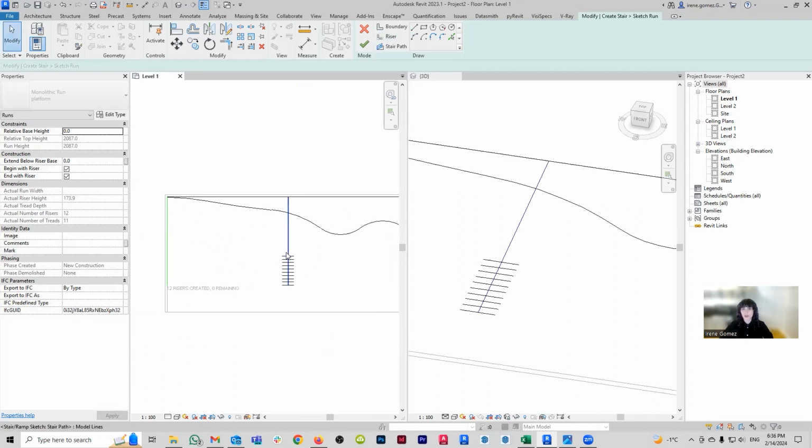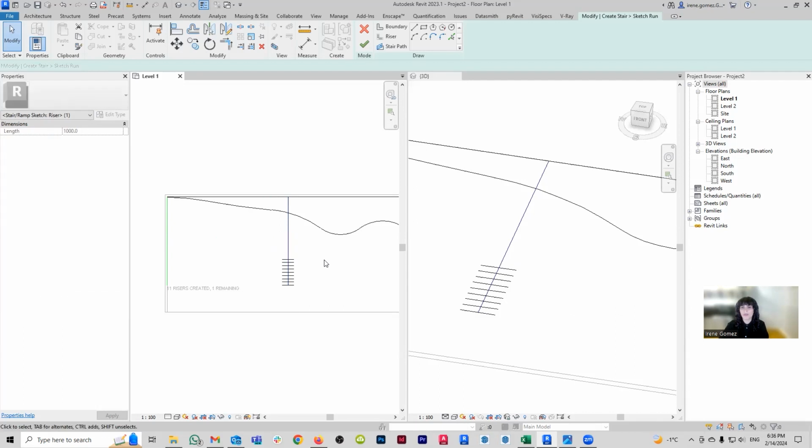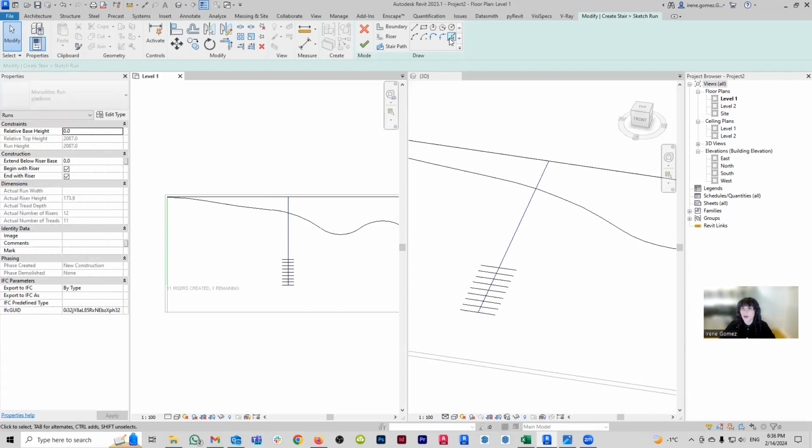Now I'm just going to repeat the same thing with the second one. Again, if you look at the reference image, you have these big steps, and then you have the little steps in between. To make this process faster, for this second step, instead of drawing it from scratch, I'm going to choose pick line, and give it very little offset, like literally 1 millimeter, 2 millimeters.